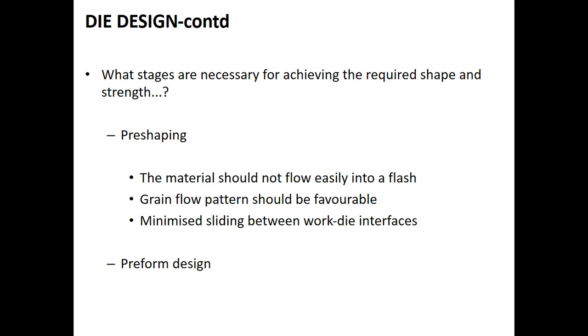Again, the grain flow pattern should be favorable, and again there should be minimized sliding between the work die interfaces. So these 3 points you must keep in mind. The material should not flow easily into a flash, the grain flow pattern should be favorable, and minimize the sliding between work die interfaces.